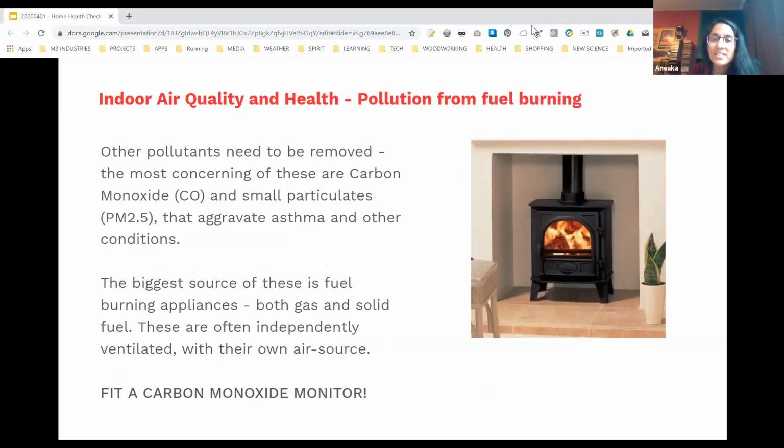I guess the other benefit of insulating is that it reduces heat loss, so it'll be easier to keep your home warmer. But you're right, that's also why it's important to try to create a continuous insulation layer so that you don't get cold points at junctions that then give you mold problems.